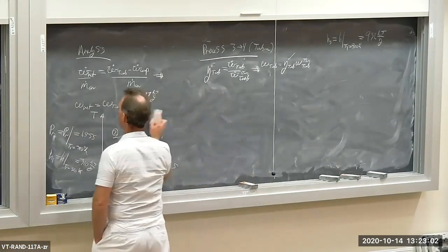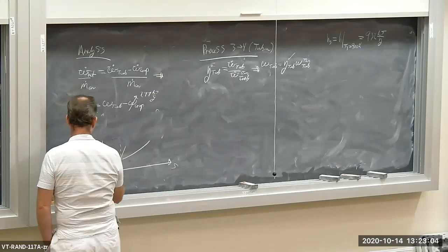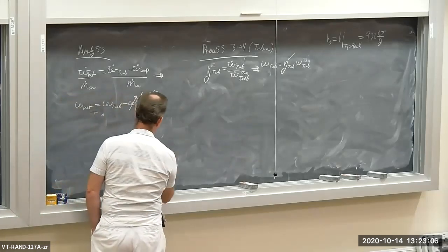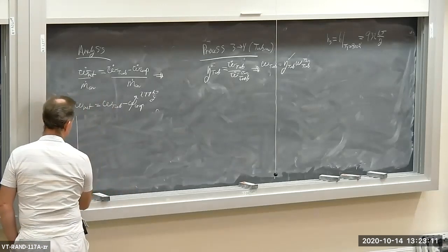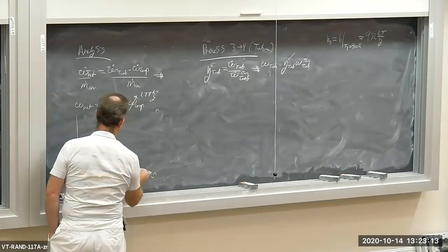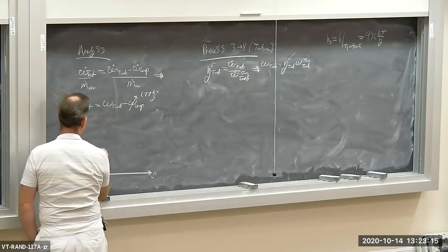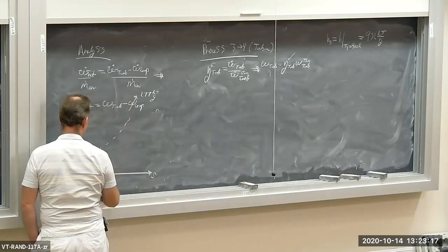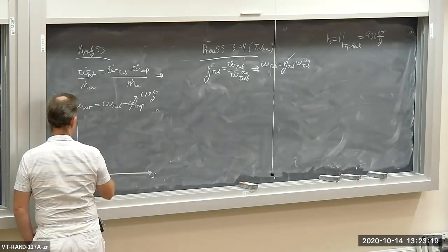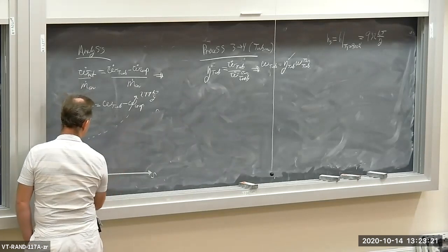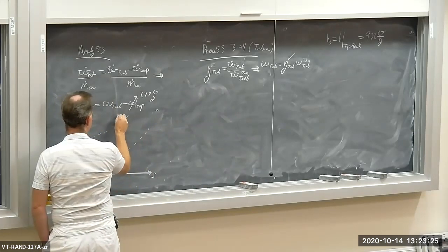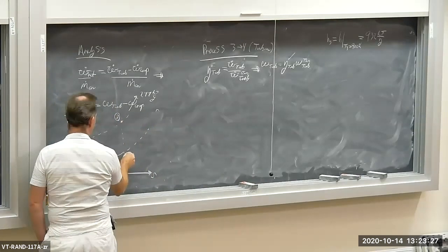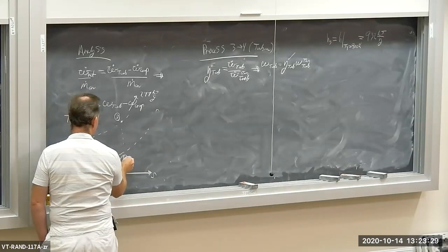So let me put up the TS diagram for the turbine. Here's S, here's T, and here are my P min and P max isobars. Here's state 3. The isentropic turbine goes down to 4s.